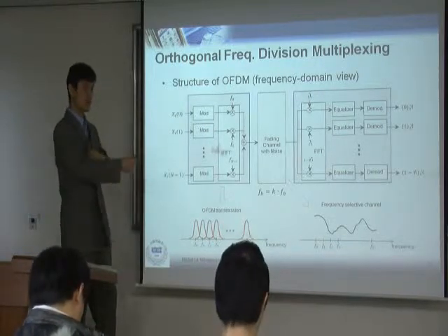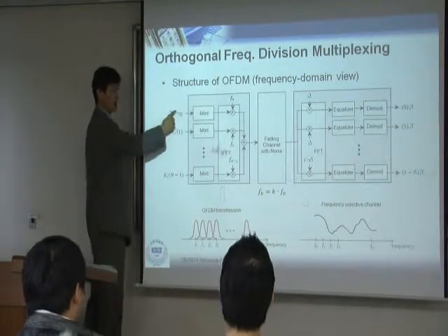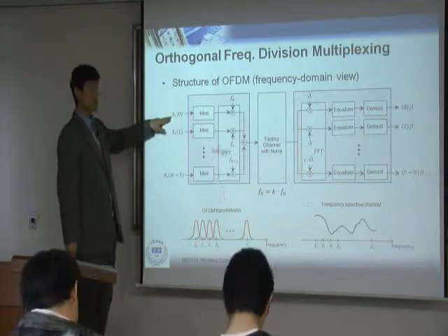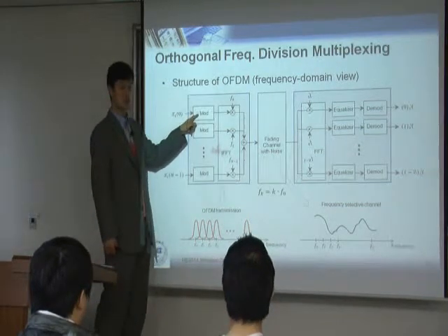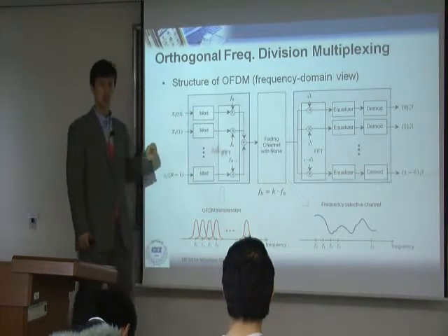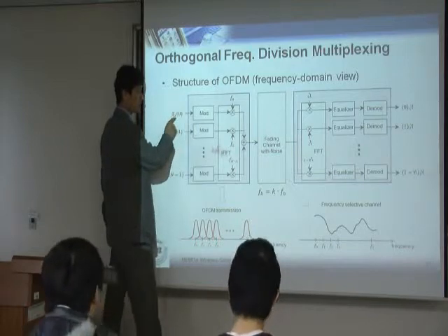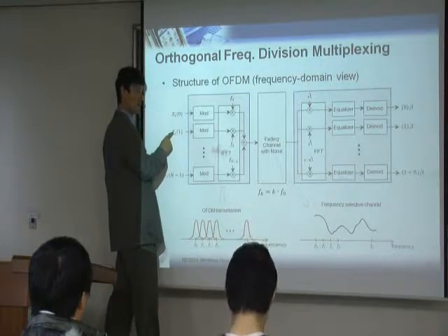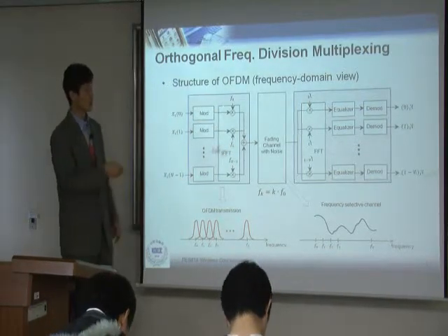Let's look at the OFDM. OFDM basically follows the same concept. Here, we have n samples from x0 to xn-1. Capital X means the frequency domain, so we have n frequency domain samples. Each one now goes to a different modulation. You can use the same modulation, in fact, but you can use a different one if you like. Each goes independently through the modulation, and then the 0th sample is modulated by f0, x1 is modulated by frequency f1. Each one is being modulated with a different frequency.